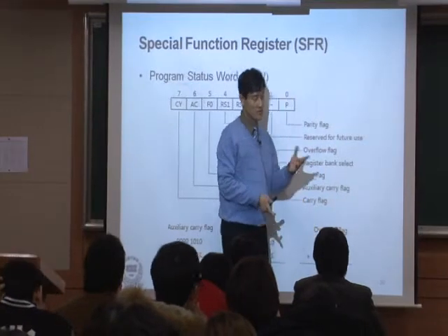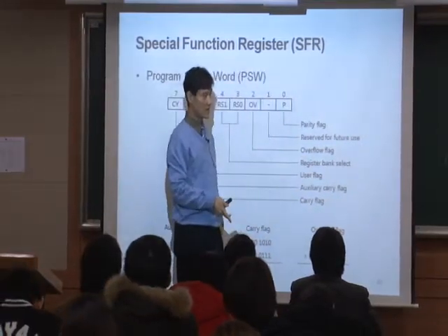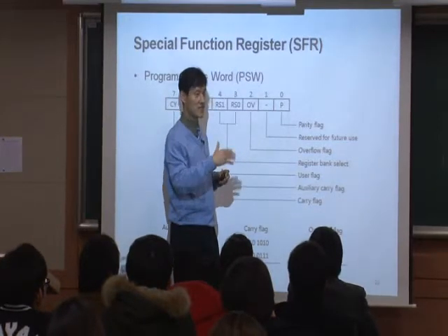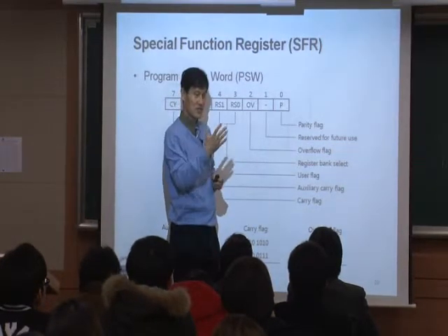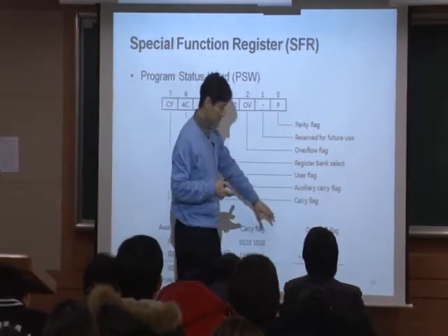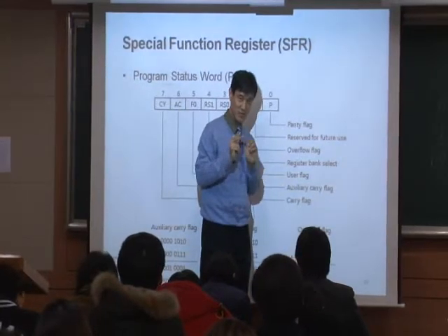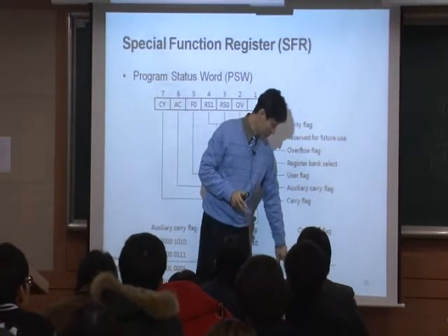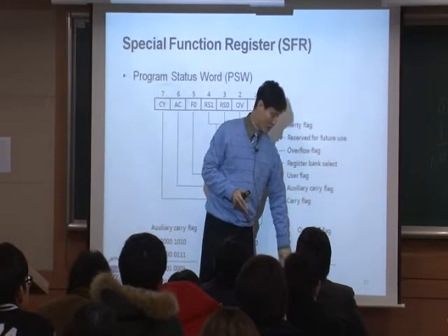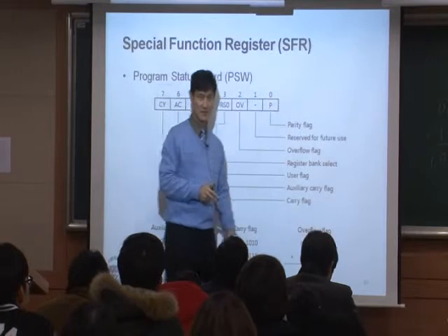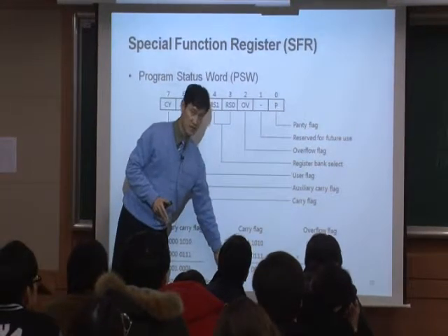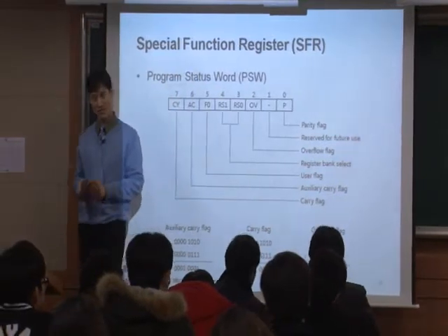The reason I said signed or unsigned is that I explained it that way because it's easy for you to understand, but the microprocessor doesn't know anything. For the microprocessor it's very simple: 0, 0, but the output is 1. The first bit, MSB, both are 0, but the output is 1. Overflow. Very simple. And if you are adding two different numbers and the output becomes 9 bits, carry. It's very simple.